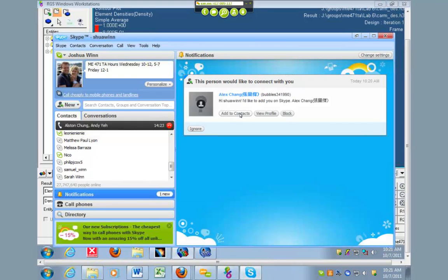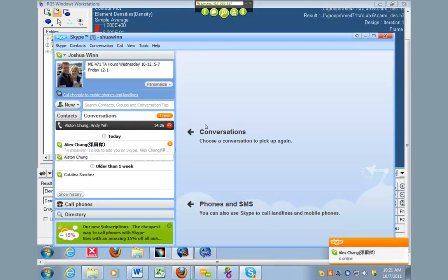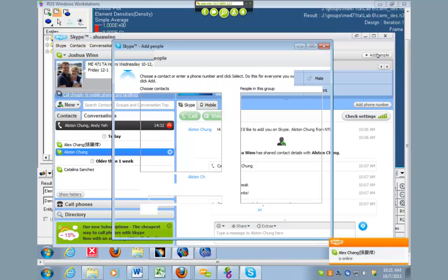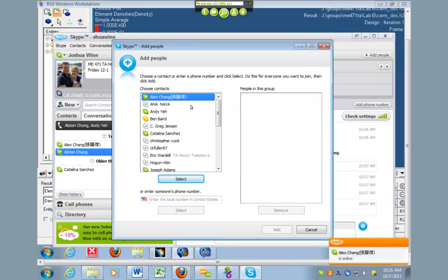Yeah, that's a good question. Do you mind if I answer that as well? Sure, go for it. This optimization is a topology optimization, so it only shows where the load paths are and where you're going to need geometry. So where the stress is. It doesn't show how much.